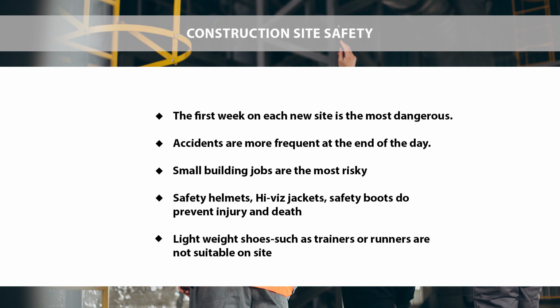Small building jobs are the most risky. Safety helmets, jackets and safety boots do prevent injury and death. Safety shoes are most essential on site, and light shoes such as trainers or runners are not suitable for site. The most important PPE, personal protective equipment, should never be bypassed.